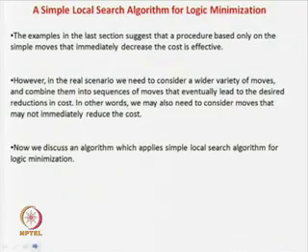So, what I am saying is that we are not exactly telling how we have got this. In case of single output, the answer was remove some literal and see what is happening and what is not happening. But in the case of multiple outputs, we have to take some solution from function 1 to function 2 and work on it. So, what I am emphasizing is that the heuristic by local search is very simple. Take a random solution, find a neighboring solution, see if the cost is good, keep it, else reject it and keep on doing it. But moving from solution space 1 to solution space 2 is a very difficult problem, because otherwise heuristic design would have been a layman's job. That is, you take a solution, take another random solution, if it is good keep it, else remove it and keep on doing it. But finding the next better solution is where your algorithm's quality will be judged.